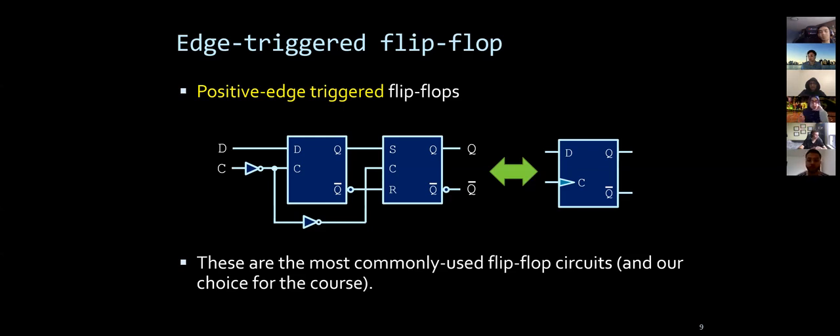So you want to have a memory cell where you know that it changes periodically, so you know when to check it when the value flips. Otherwise, let's say it shows you output 1, it keeps showing 1, you check 1 nanosecond later, it's still showing 1. So how long do you need to keep checking until it flips? You don't know without the timer. So the timer guarantees that if the value is supposed to change, then after whatever the frequency of the timer or the clock is, the bit is flipped and you will detect it. So you don't have that uncertainty on how frequently you need to check. 5 times, 10 times, it's not clear otherwise. So the clock is really needed for this circuit. You can't really manipulate them efficiently. They would have memory even without the clock, but it's not very usable, right?